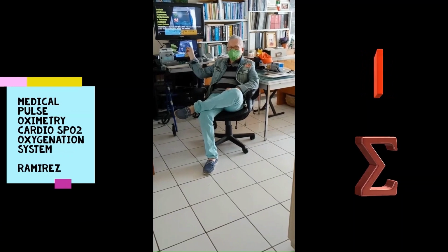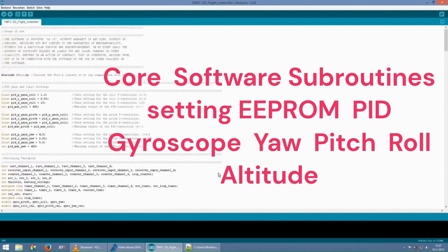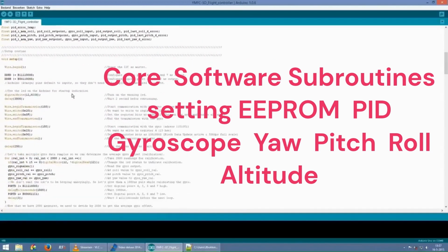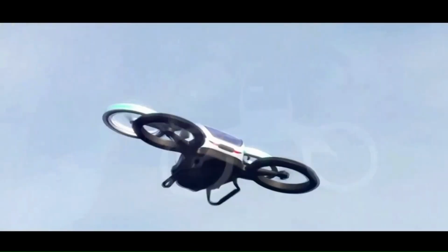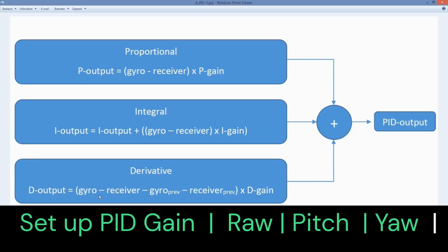The main software model and modules include the Wire.h library to establish gyroscope communications. It includes the EEPROM.h library to store info into the EEPROM. The following parameters are also performed and included. First, set up the PID gain and limit settings.